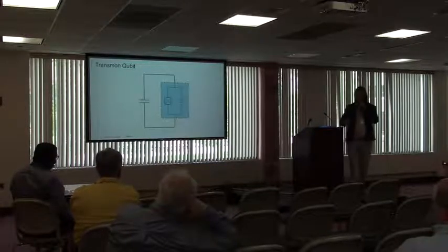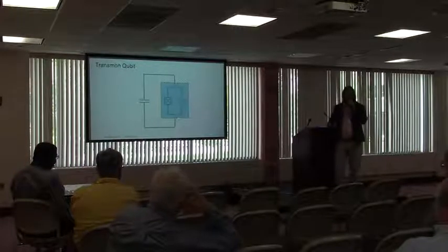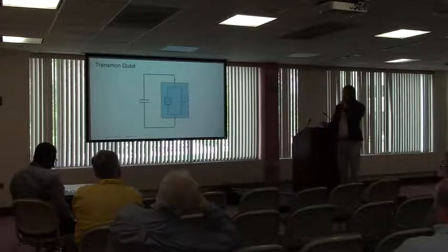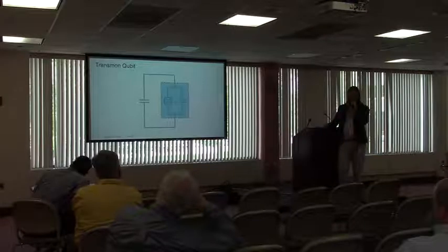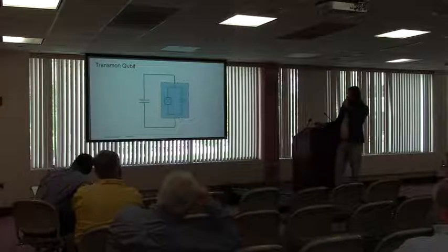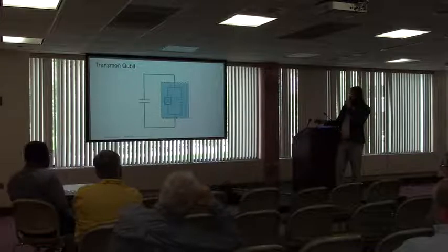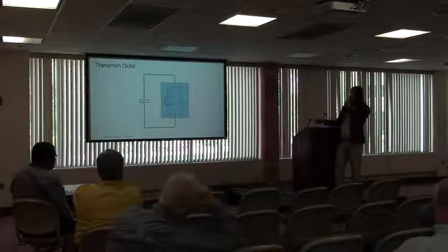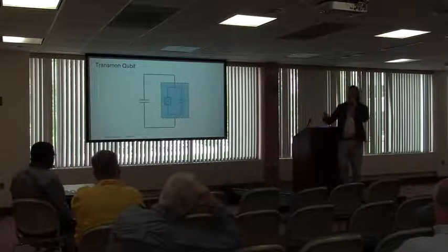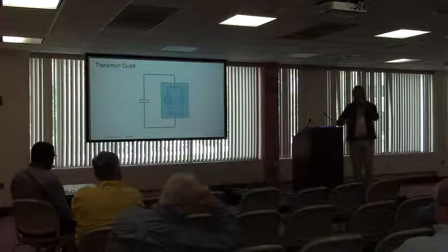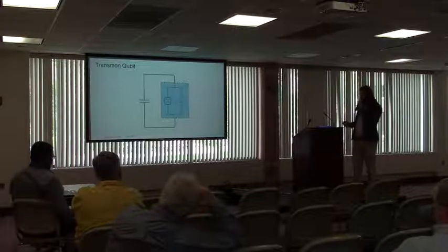So now, how can I build a circuit-based qubit out of it? There are multiple ways, but the qubit that has shown the most potential so far is called the Transmon qubit, which is basically a capacitor brought in parallel to that Josephson junction. This shaded box is going to give you a qubit. And then you use additional capacitors to couple this qubit to the outside world. For example, it could be coupled to a resonator, which can either couple to other qubits or an I/O port.